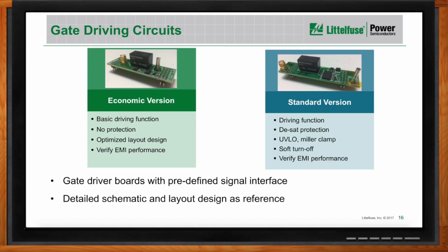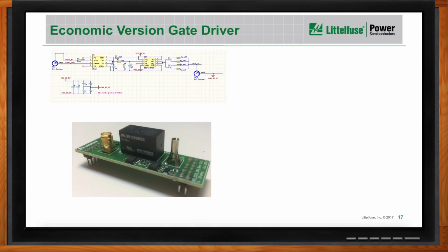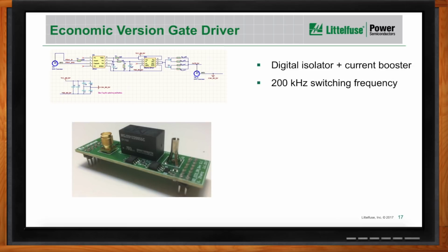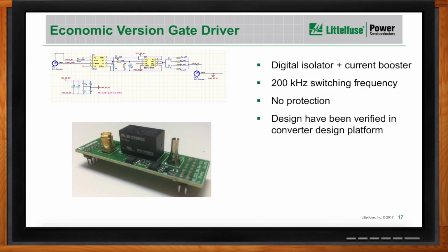Okay, so can you give me a few more details? Yes, for example, for the economic version gate driver, we use a digital isolator plus current booster solution just for the basic driving functions. This gate driver can work up to 200 kHz switching frequency to drive our devices. There's no protection, so the user has to implement their own protection. The design has been verified internally in our lab in the converter design platform for many hours of continuous operation. It has the same interface as our standard gate driver.